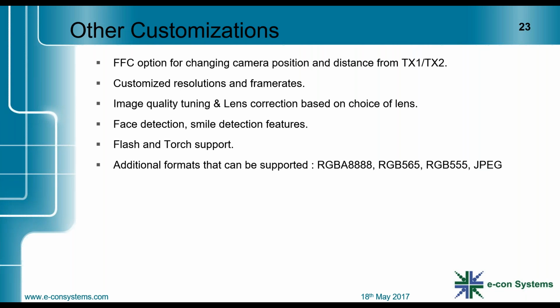Other imaging formats such as RGBA, RGB 565, 5555, and JPEG can also be supported using this MIPI camera, because we have an onboard ISP which can do all the processing without offloading anything to the GPU. Sorry, the CPU in the TX1.